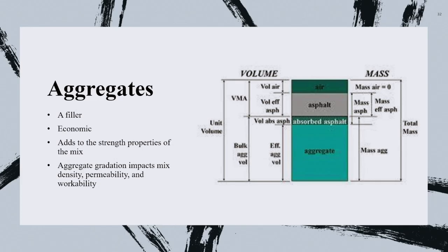Here, your asphalt, if you use, let's say, 5% free binder content or asphalt concrete, and you add it to your aggregates, do you think after you mix it, you'll have still 5%? Some of it will enter because, yes, it will be absorbed. This is a difference in color between aggregate and asphalt. You see a strip with absorbed asphalt. Do you see this? This is extremely important, which is, if not calculated, you will end up with a much lesser binder content in your mix than what you think you already have.